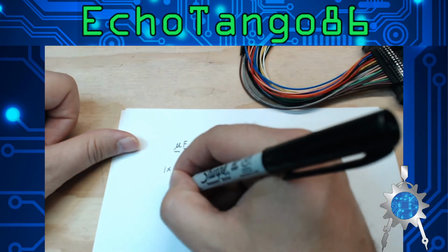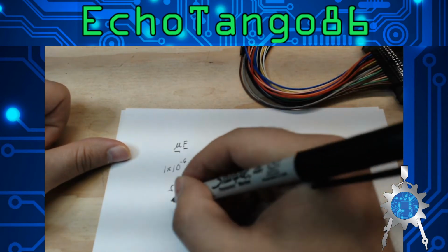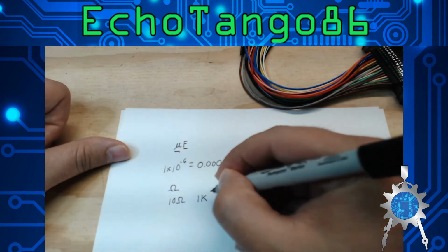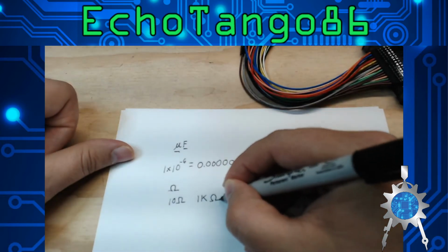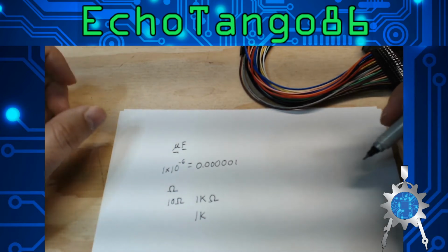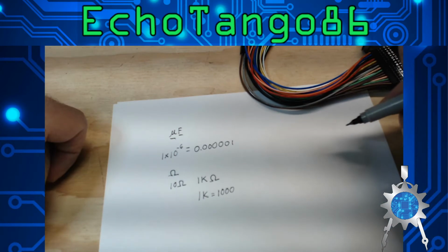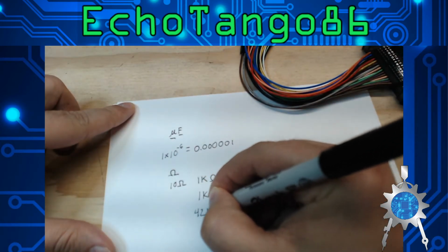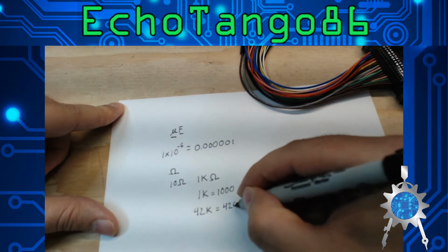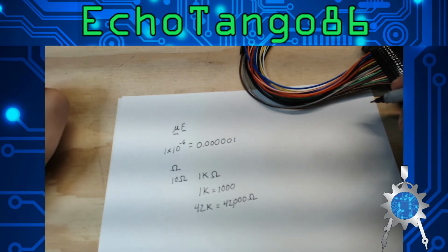Now you might see this symbol. That's ohms. That's resistors. All resistors are based off of ohms. You might see something that says like, I have a 10 ohm resistor, or I have a 1K resistor. Sometimes they'll include the ohm symbol, so the 1K ohm, or they'll just write it as 1K, 2K, 10K, 100K, whatever, and all numbers in between. So that K represents this, that equals followed by 3 zeros. So let's say we had a 42K written there. Well, what's that equal? Well, what you do is you put the 4, the 2 there, then you follow it by the 3 zeros. So that'd be a 42,000 ohm resistor. Does that make sense?